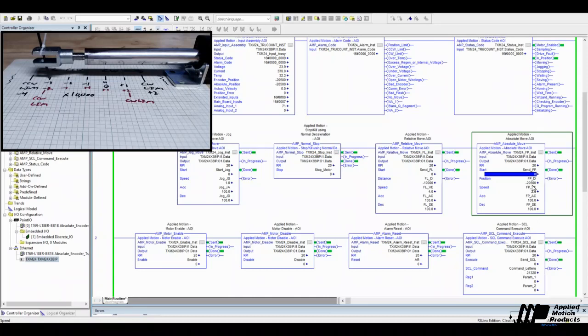Oh, and I'm realizing I don't actually have to move the motor at all. So here, let's move back to our home position. You can do this either way, but just for clarity, move back to our new home position, which remember is the old -1 position. Perfect, right there. So now, to set our limits, we use the LP and LM command.